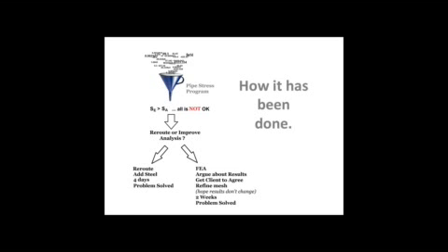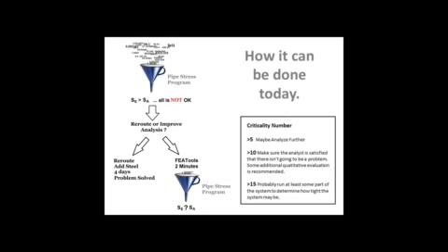Okay. In the old days, this is how this two-path process was done. We would make the calculation, we'd see that there was a problem, and we would decide if we needed to reroute the pipe or not. Rerouting the pipe involved adding steel, moving supports around, and 4 days later we hopefully had a solution. If we didn't want to go that route because it was a real pain to the project, we would say we want more analysis. We'd build an FEA model, we'd argue about the results, we'd try to get the client to agree, we might refine the mesh and hope the results didn't change, and then 2 weeks later we would hope that we had a solution.